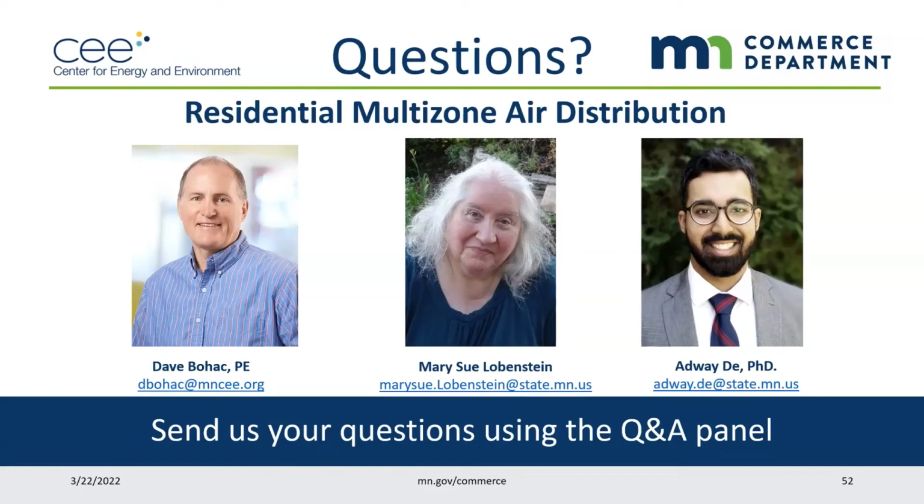So that's a very good question, and one that I have talked to our staff that work on new home certifications about. Most new homes now are using HRVs or ERVs, and they connect the ductwork on supply air and exhaust air into the central air distribution system. So they could either be both in the return or in return and supply.